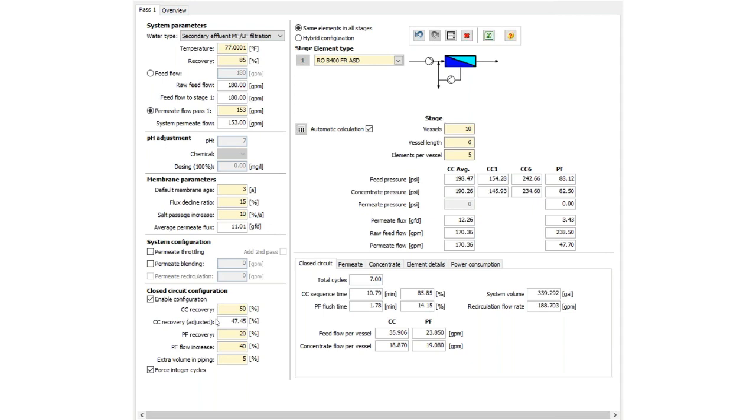And I should highlight 9 times out of 10 are easy applications. And when I say easy applications, I would say relatively high recovery and higher flux. You don't have to change these set points. So the times you're going to want to go in and change these set points is brine recovery or wastewater reuse, and we'll get into those details in a minute.